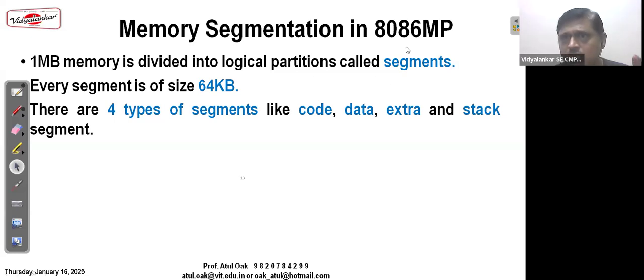Every partition is called a segment. The size of the segment is 64 KB. It is fixed. Okay, you cannot change this value. And 4 such segments are used in 8086: the code segment, the data segment, extra segment, and stack segment.